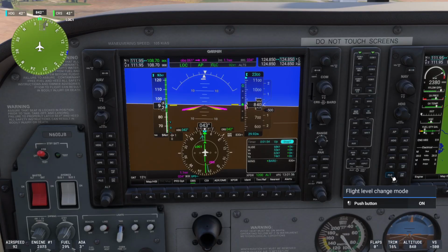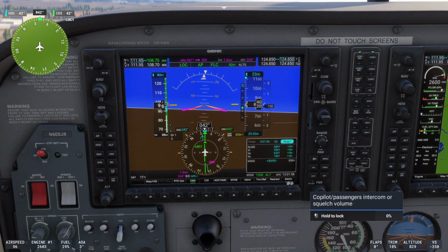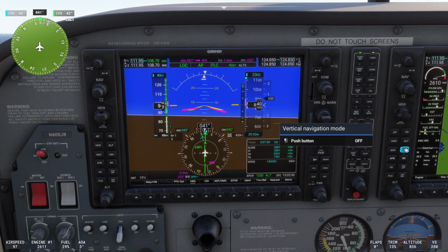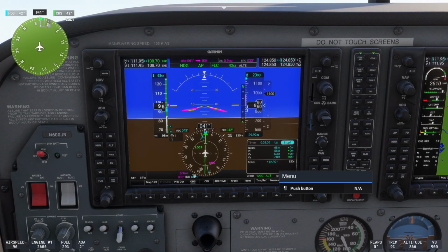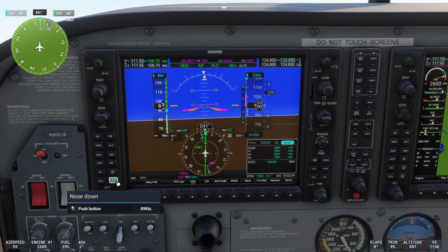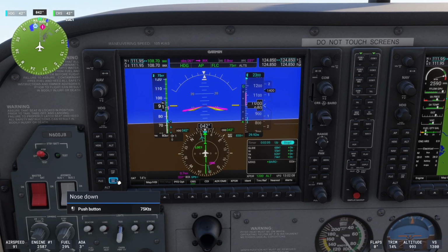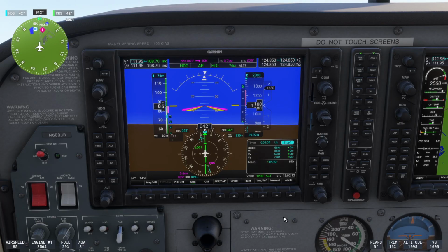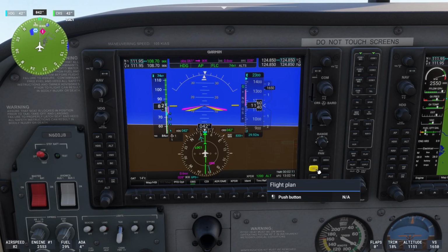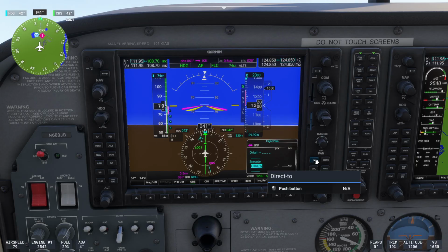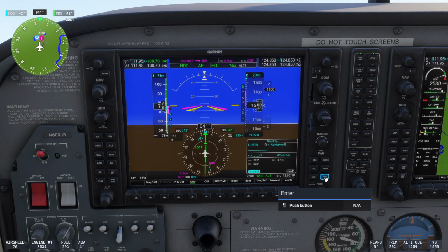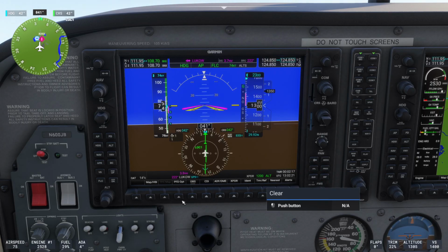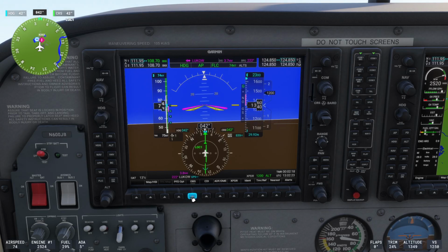Okay, so coming up on minimums, let's go ahead and go missed: power up, pitch up, clean up, contact ATC, tell them we're going missed. And we'll go ahead and get that missed approach set up. So we're going to climb to that 2,300 feet and then make that right turn. We'll go ahead and put direct to Lookout into our GPS. We already have that in our flight plan, so just direct enter it. And there you go, that RMI needle is now starting to point to Lookout.